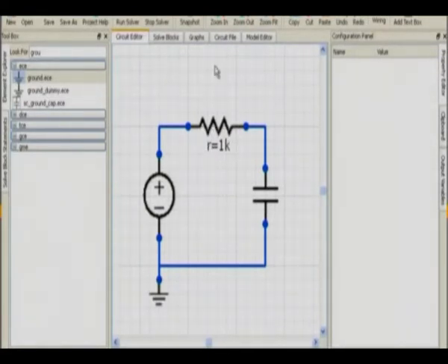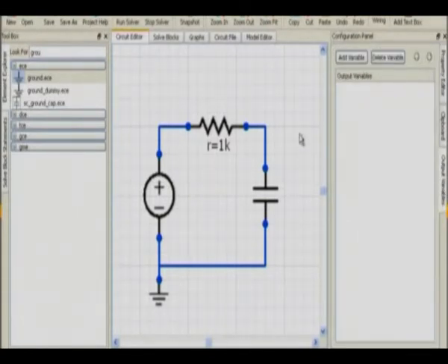All right. Let's move on to output variables. We would like to define some of these variables for viewing as output variables. So go to the output variable tab, click on add variable, and then click on one of the wires that you want to see, the node voltage. Okay. All right. So that has come. If you see, there is a default name that is generated, and then there is something called a keyword node V of something something. Right.